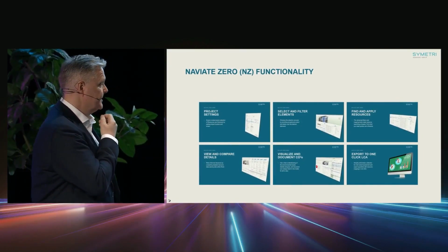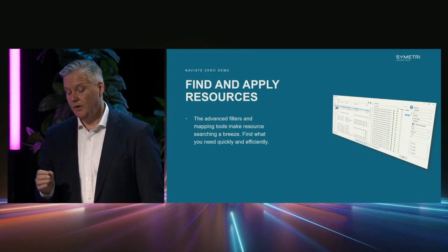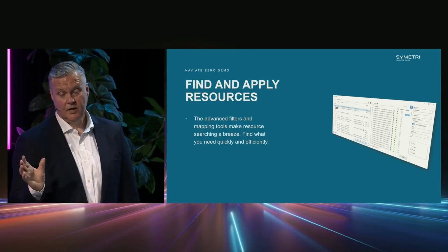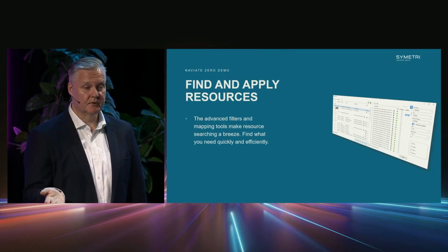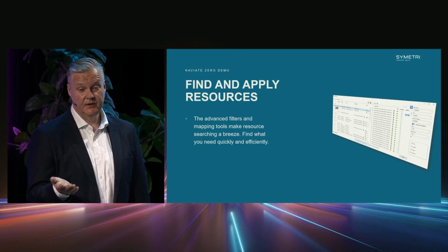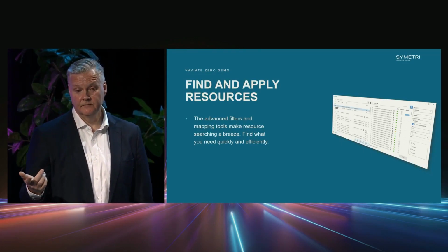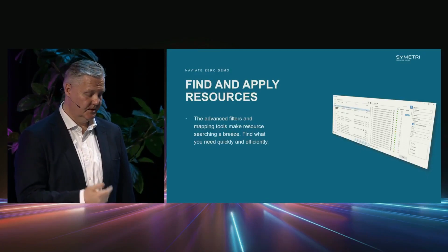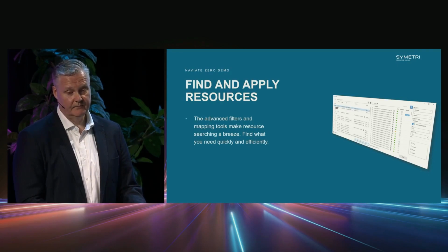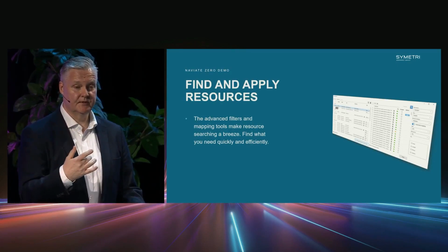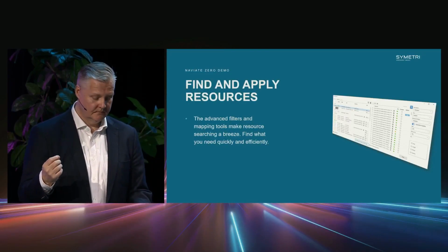Next part is find and apply resources. So you have access to many thousands of EPDs and resources, and it's difficult to work with. So if you know you are going to work in Sweden with a project there, you of course pick the data resource Boverket. That's the standard in Sweden. Further on, what area comes default from the settings, so you don't need to consider that. But if you did wrong in the beginning, you can change it here.